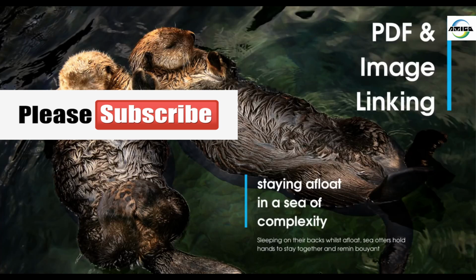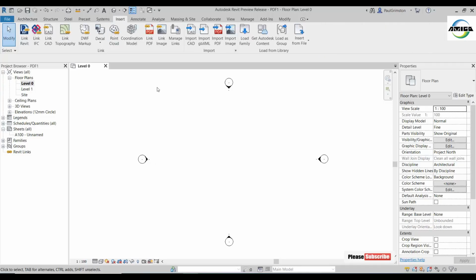The first feature we're going to have a look at in Revit 2021 is the ability to link PDF files and also image files. On our Insert tab now, we have Link PDF and Link Image. Previously, we were able to import PDFs and import images, but the functionality now is the ability to link them.